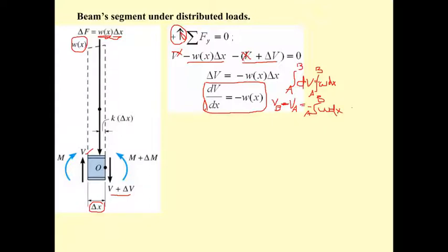Or if you write it clearly, the change in the shear force is equal to minus of this integration. The integration is the area under the function, so we can conclude that the change of the shear force is equal to minus the area of the distributed load.